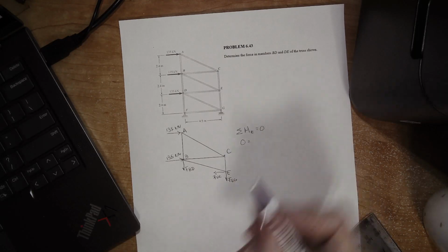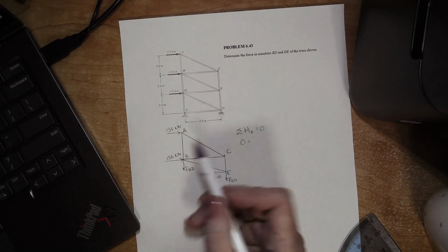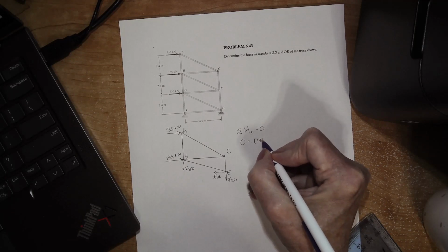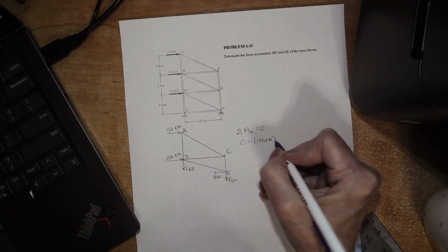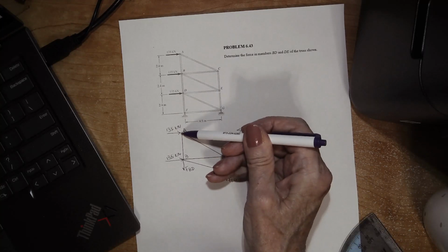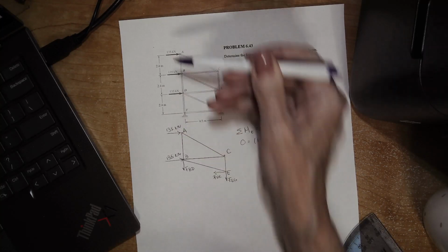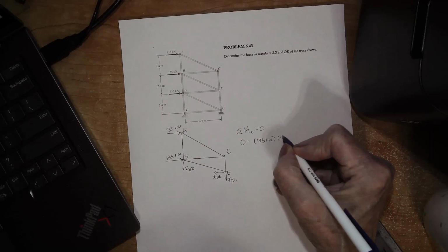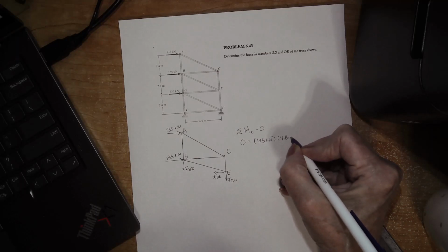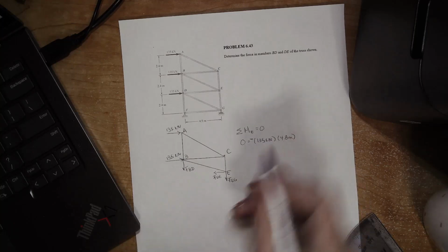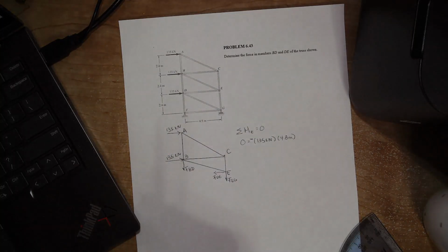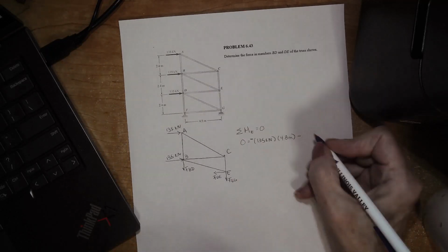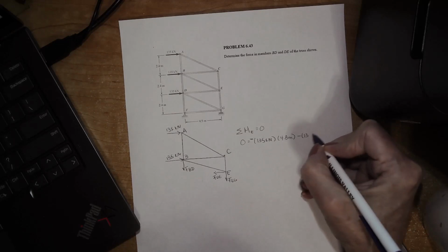And so we know about point E, we'll have a contribution from our 135 kilonewtons. This 135 kilonewtons applied at A is 2.4 meters above B, and B is 2.4 meters above E. So we have a total vertical distance of 4.8 meters. We know that it is a negative contribution because it would create a clockwise moment. And then also we have the 135 kilonewtons applied at B.